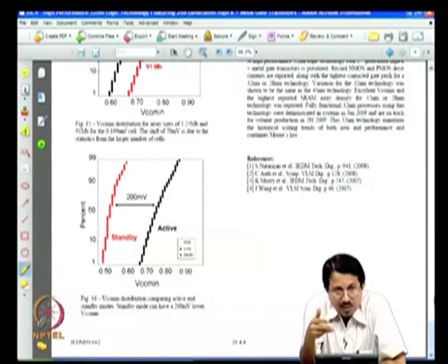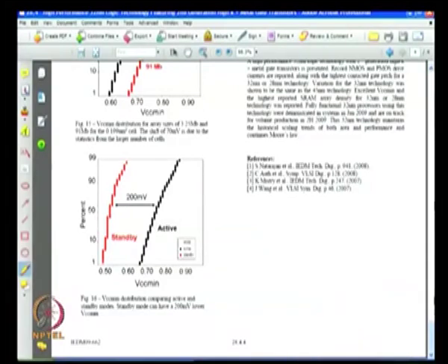Similarly, in the interconnect arena, we have gone from aluminum and conventional silicon oxide to doped silicon oxide, copper, and thereby minimize the RC delay of the interconnects very significantly. So, hopefully now you should be able to read up any CMOS technology paper and be able to understand that based on all the discussion that we have had so far.